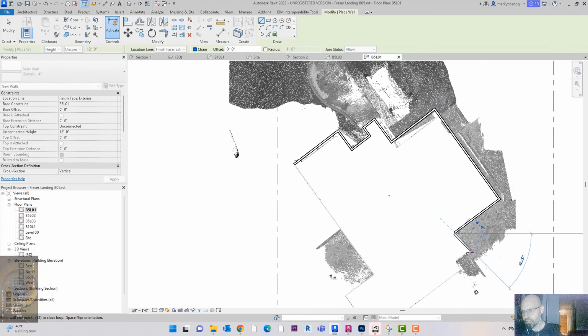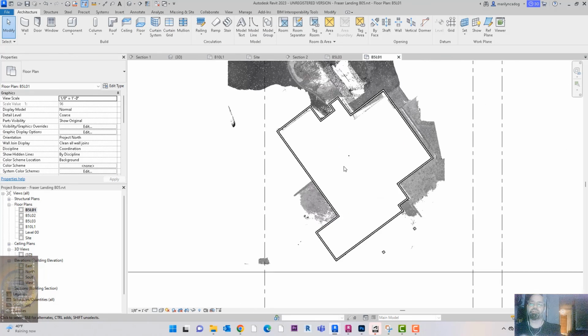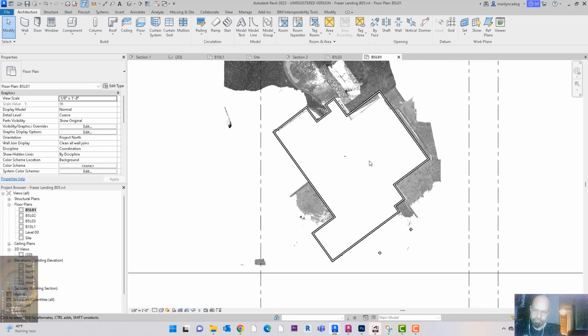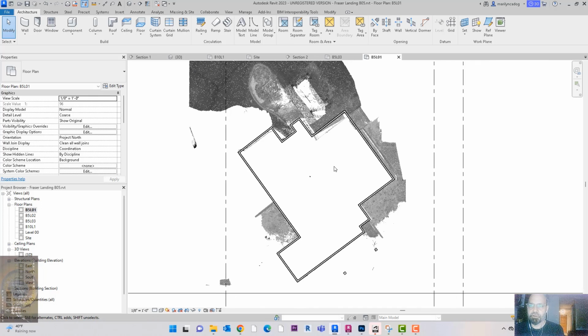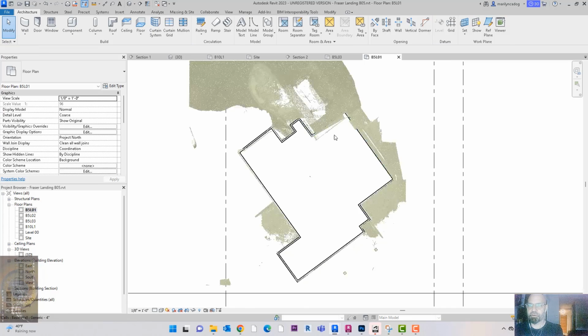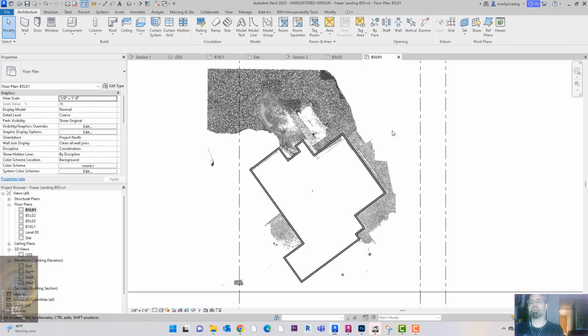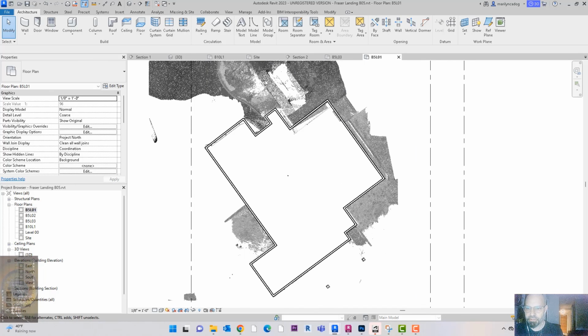So what you would want to do is you scan the entire site like my man Richard Johnson, who did the scan. So you do the whole site, and then you come along and do the interiors of each individual building. And then if I went back to the site and scanned the interiors, I would use the little scans that we have here and merge those together, because putting the interior scan inside the entire site model would just make it way too chaotic.